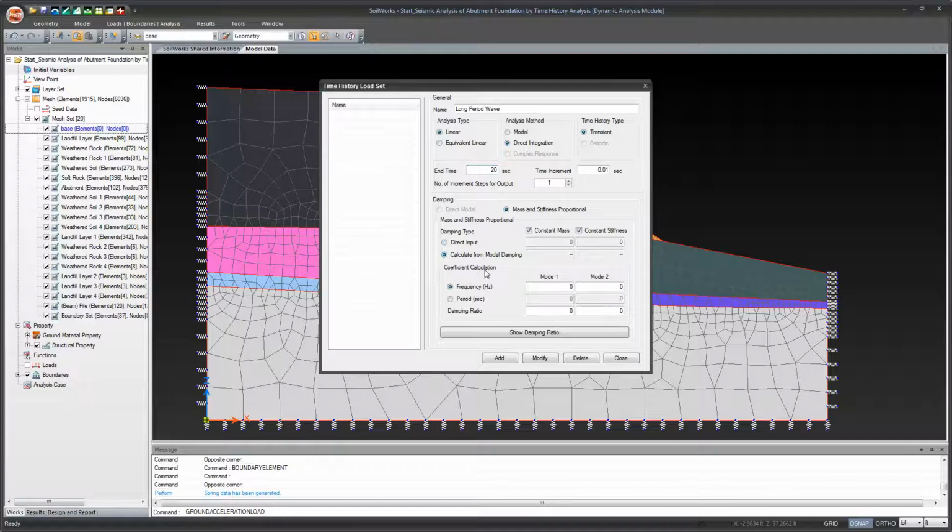And then modal damping, so here we'll input manually. For the frequency, let's make it 1.7897, and I'm getting these values from the tutorial that was provided. I gave you all a copy of this, so you can look into it further afterwards. These are just the default values assigned by the tutorial. Depending on the wave you're using, these modes will differ. The second default value given is 3424. And then the damping ratio, which is the same for both modes, is 0.05.